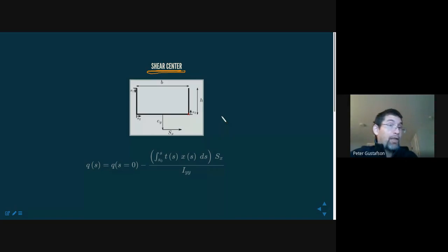And I do talk about that in aircraft design class. There are ways to mitigate stall so it's not a sharp stall. In fact, your goal is to have the wing roots stall first and then have the tips not stall so that you can maintain roll control kind of well into the stall region. But that's kind of the level we describe it. We don't go into much more detail than that.